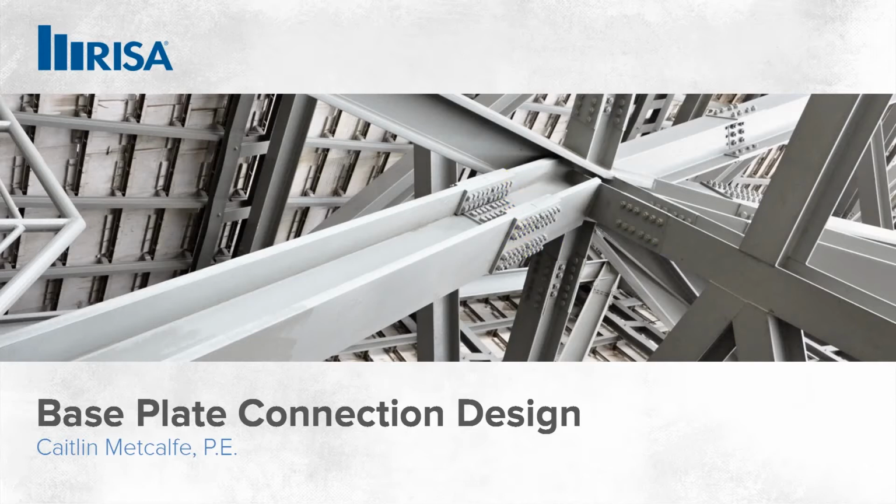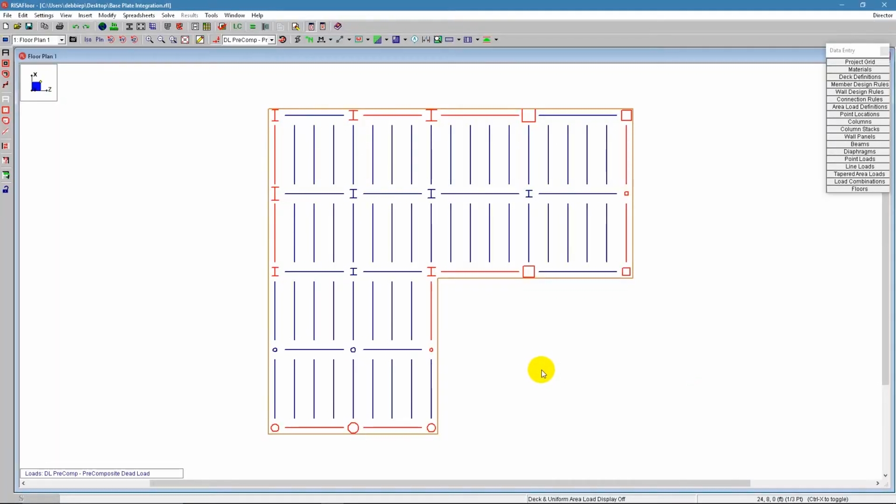Let's go ahead and get started by taking a look at this RISAFloor model that I've already created. It's a very simple model, and I created a mix and match of different column options to show you the different options available for baseplate design once we get into RISAConnection. So you'll have red members designate the elements that are part of my lateral force resisting system, and the blue elements represent my gravity members. You'll notice I have columns that are wide flange columns, I have pipe columns, and I have tube columns here.